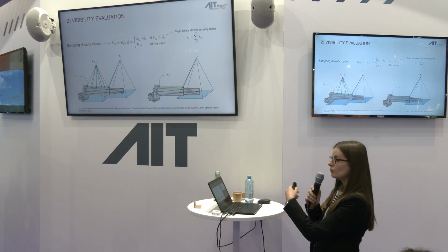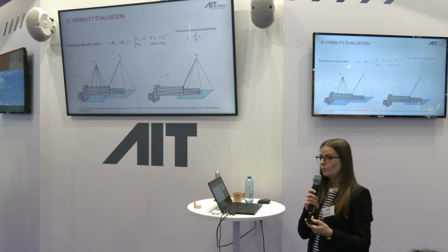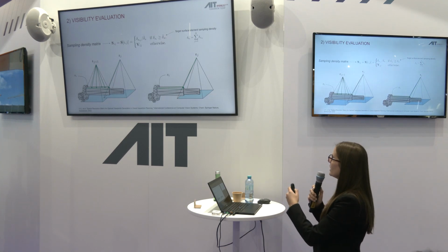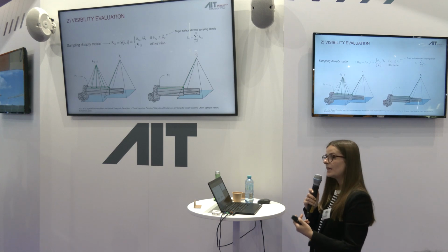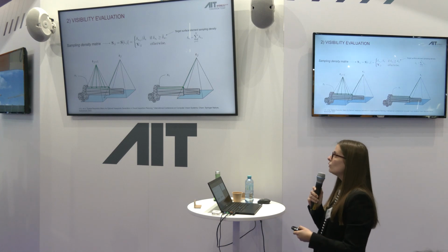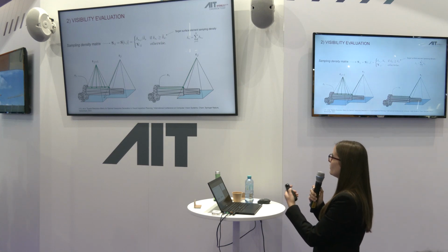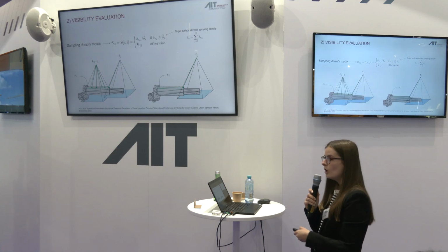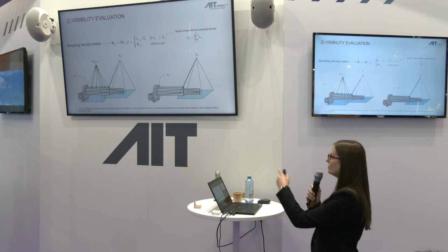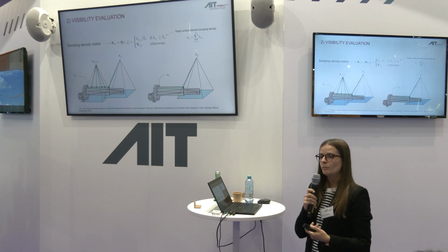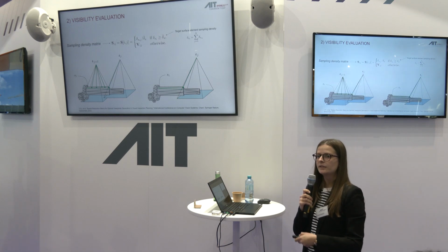So when we are in the situation like the one on the left, in which you see that there are two inspection poses, in which one inspection pose is covering for real the object with the surface element density that we want, then we use not 1 or 0, but a normalized value. So the normalized surface element sampling density. When this is not the case, like on the right, then we use the standard visibility matrix because we prefer to cover one face with at least one ray than not see it at all.